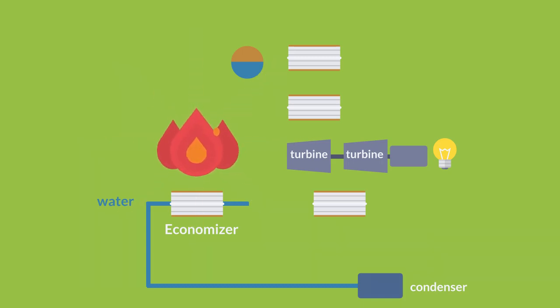The boiler or steam generator is used to create steam by applying heat energy to water. In general, it is formed by a bundle of multiple tubes in the combustion chamber walls. The steam generated in the water tubes is collected in a drum, which is a reservoir of water and steam at the top end of the tubes. The drum acts as a phase separator for the steam-water mixture.